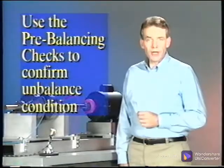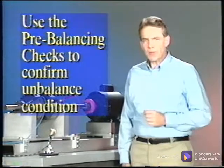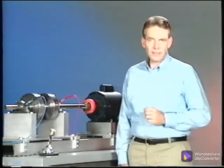Use the pre-balancing checks to confirm unbalance is the problem and determine whether single or 2-plane balancing will be required. Check the manufacturer's recommendations for weight planes and weight placement.